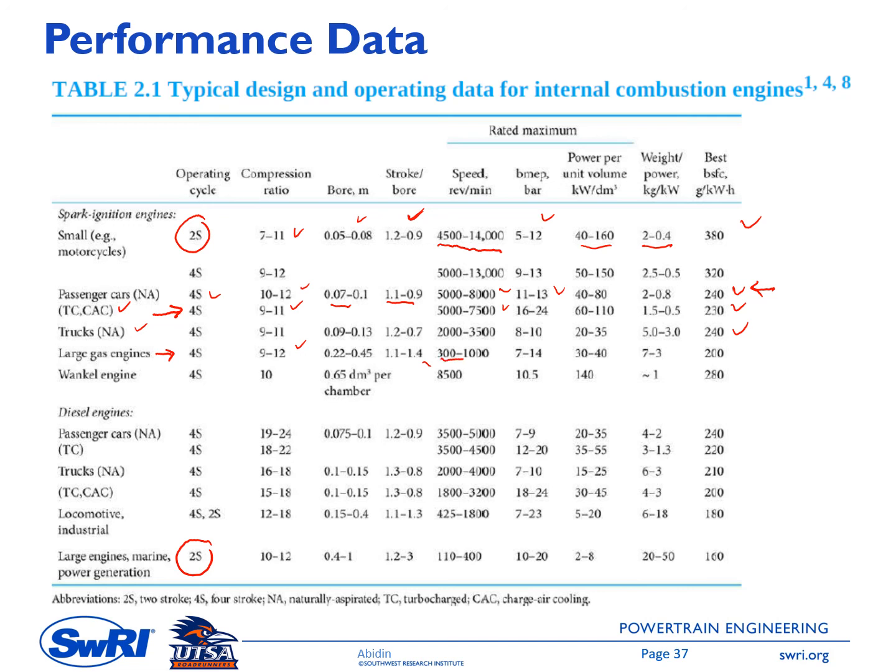Large engines usually have a lower engine speed. And then another important thing here, you can see that if you have a larger engine size, then it has a better efficiency, or a better PSFC. This is because of the lesser importance of the wall heat transfer. It's just one of the reasons. Another one I think is the engine friction. So we'll learn this one in more detail in chapter 11, I think.